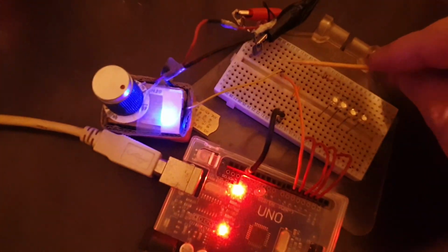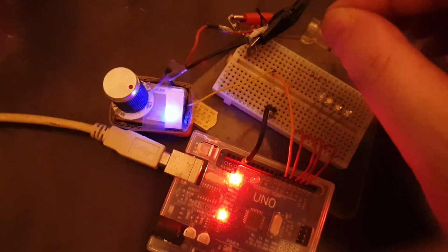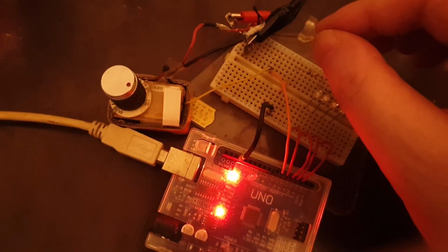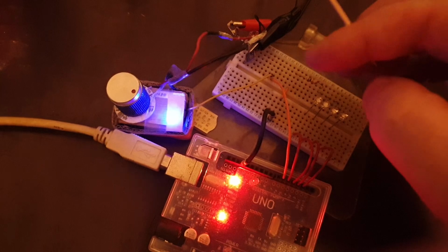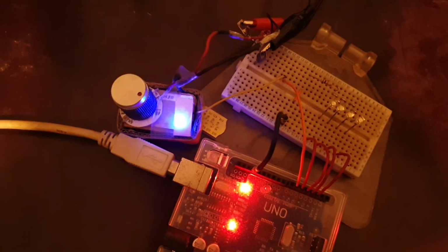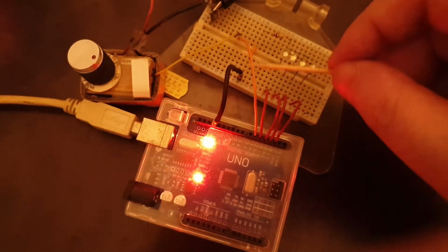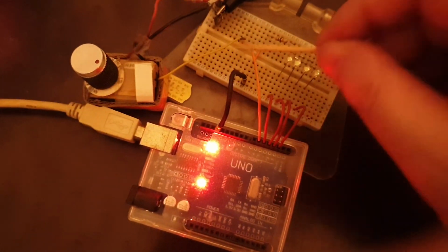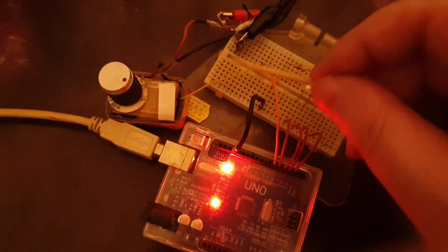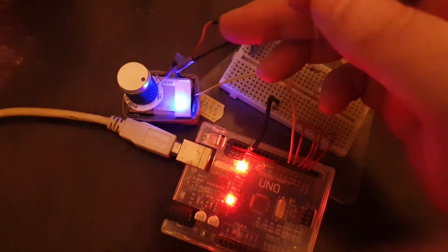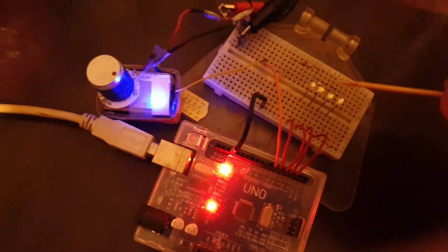Instead, you can do the same thing I'm doing here. Instead of this oscillator, you can get a wire and put it manually to 5 volts and to 0 volts, and do it like that manually. Or a switch or a button, pressing a button and switching between 2 rails, a button with a resistor on it. So this is the line on pin 6, next in line. The next pin here on the Arduino is pin 6, and this is the wire from the oscillator. I could put this wire directly there, but this wire is in the way, and these wires are a bit stiff, and I was afraid to make a big nasty short there, and I didn't want that.